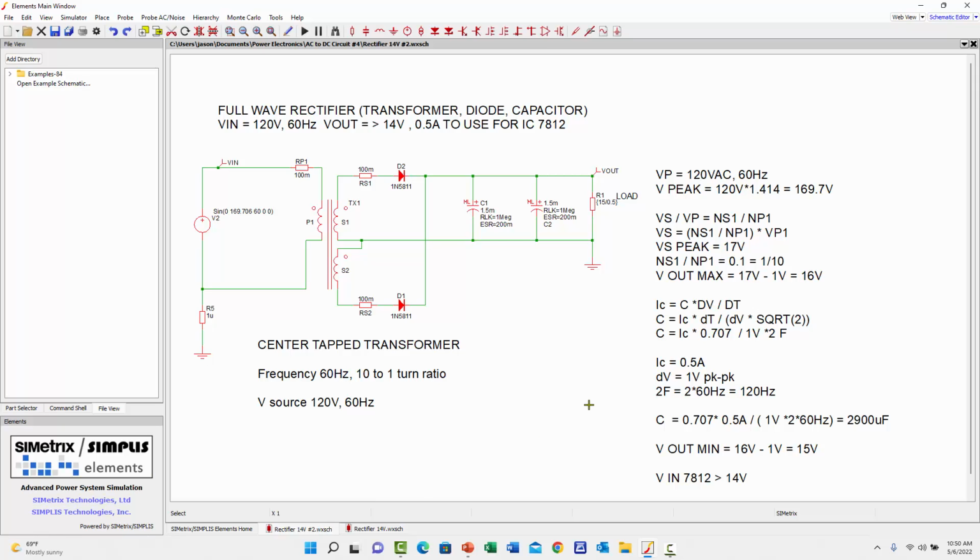So this is our complete circuit that converts from an AC to a DC source, and we're putting in a tantalum cap or aluminum type of capacitor here. The first step, as you already understand, is that we're converting and getting a rectified waveform around 16 volt peak. Now our next step is how do we select the capacitor to get the voltage above 14 volt and control the ripple voltage across the output.